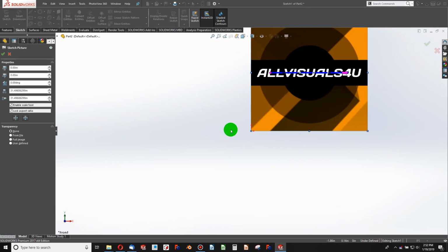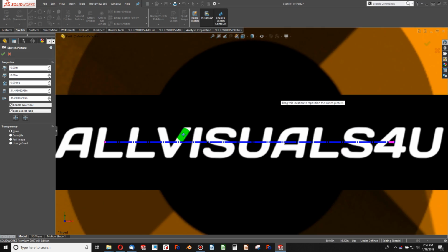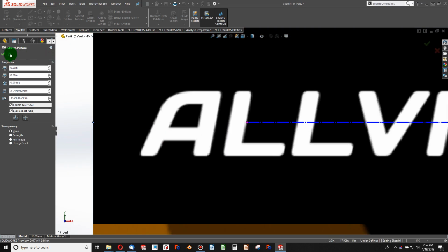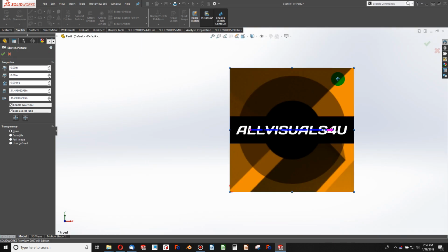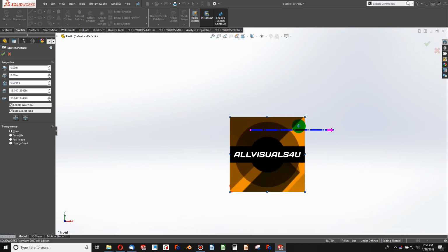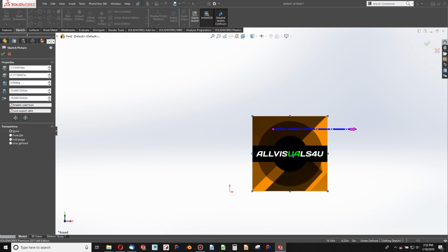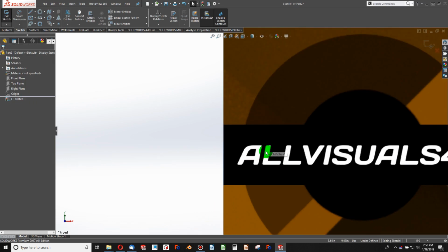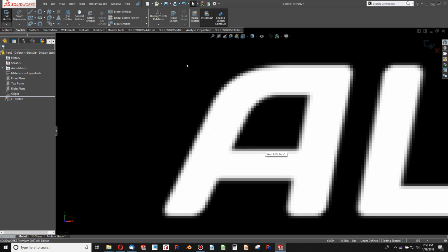In this case, this will be the logo of All Visuals for You, the channel that I am working with, and I simply click the box, or I have the options to rescale it, drag it anywhere that I want to. So once I get happy with the position, I'll choose this arbitrary position, and I can begin sketching. Now normally in SolidWorks, the goal is always to fully constrain your sketch. In a case like this, it is pretty difficult when you have things like this curve that is not a constant radius.